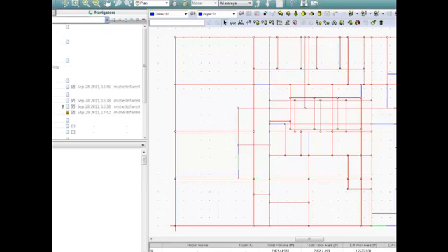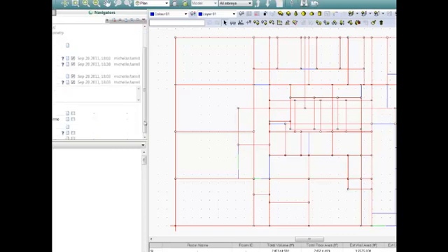And then for our final element that we're going to look at is back in Gaia. But again, all of these tools offer this quick iterative feedback that will help you with your design. So going into materials, again, I have the option to change my glazing, change my opaque constructions like my walls or my roof or these other details, ground varying surfaces, which means that if I have a portion of the wall that is above ground and below ground, I can set that all up.